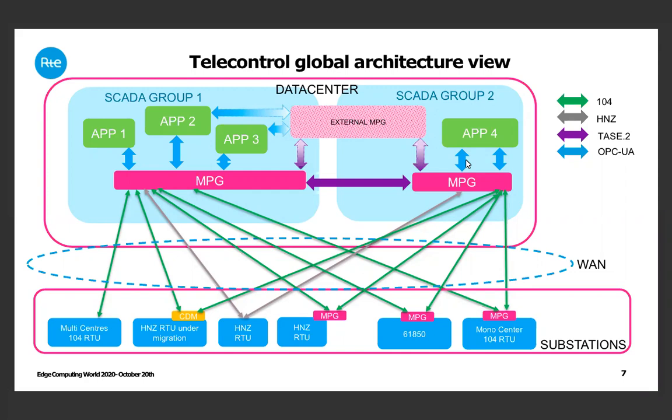So you have, of course, the SCADA, but you have also a tool that we are developing with the Plasma project. That's another generation of asset monitoring, in which we will be able to gather far more information than what we are gathering with the SCADA, so that's for the asset management. And we have also some automation that may be implemented at various levels. It may be at the data center level, or also at the substation level to be able to control the behavior of the grid based on various events that could occur close to the edge, actually.